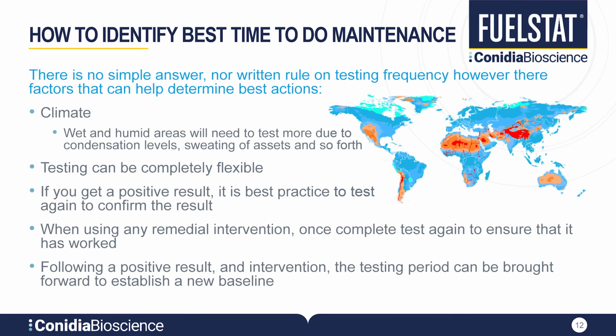While there is no simple right or wrong answer or a clear mandate that dictates how frequently fuel should be tested, there are a few additional areas to consider to help you find the right approach for your own operation. Humid and wet climates can enable the growth of microbiological contamination, as water can enter the system through environmental factors such as condensation. Testing does not have to be a regimented practice. Actually, it can be quite flexible to help meet any growing concerns you may have about specific assets or locations, but at a minimum, using a testing pattern of twice a year is often advised.